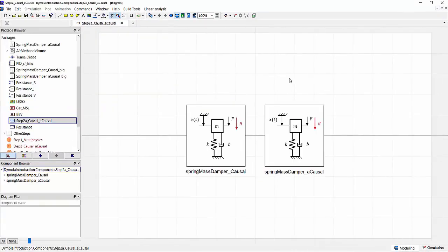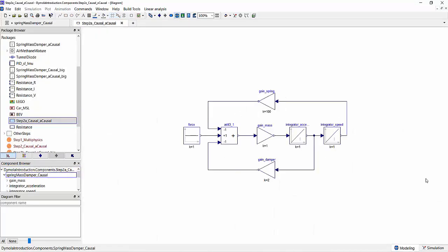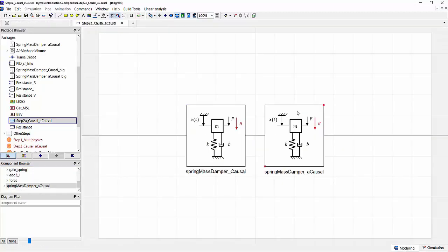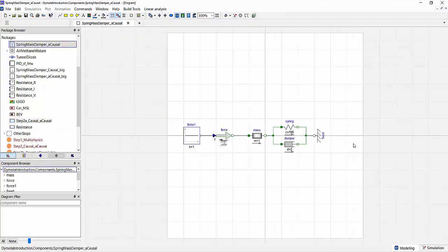Now, there are two fundamental ways of modeling such a system. The conventional way would be to use a signal flow based diagram, in which we take our physical equations, we Laplace transform them, and then we can map out the system behavior by looking at signal flow between different components. This has been done for many years and works. Let's contrast that with the model that we build in Dymola, which is built in a very engineering-friendly fashion. We can identify all the individual components just like we see them within the sketch that we saw previously.